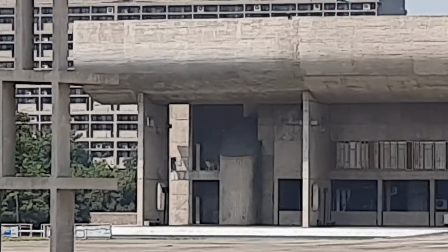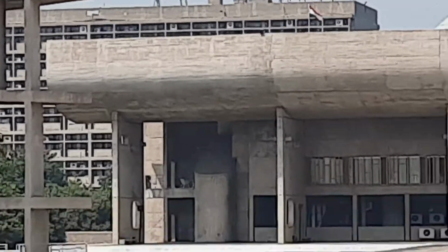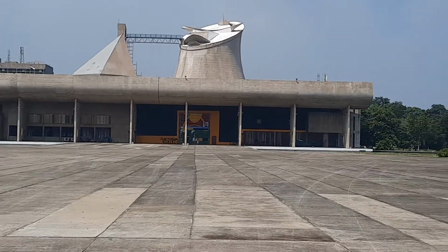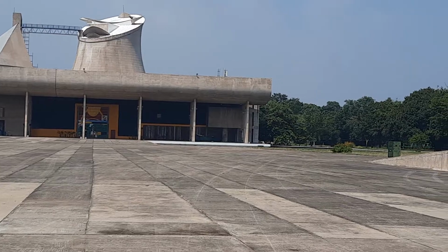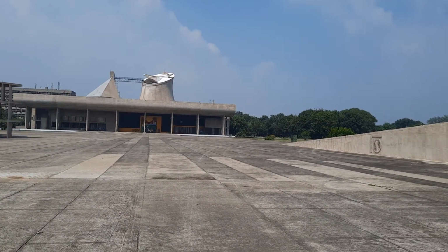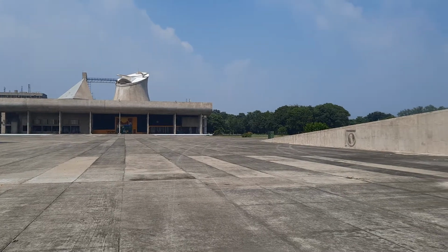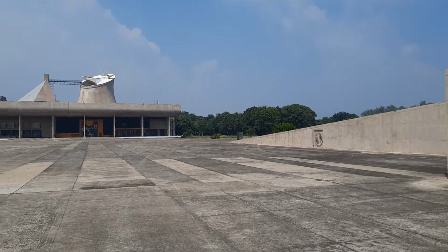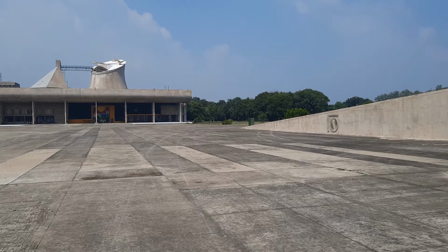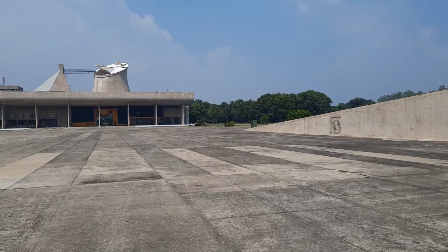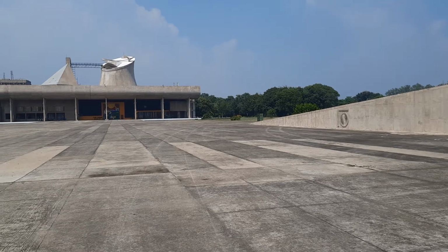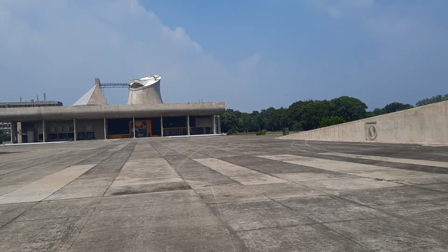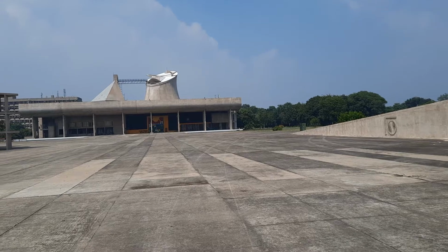You can see the punctures. These were the most important architectural feature of Corbusier's design. The vertical blades, the brise-soleil, to cut the sun, to cut the Indian harsh sun. And we are standing here, it's almost 36 degree temperature here. So you can assume the time of May, June, July, when temperature shoots up to 42, 44 or even 45 degrees Celsius here, because it's North India, the Great Plains of India. Here sun comes directly and the temperature is usually very high in summers.